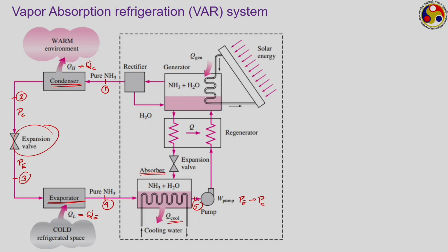Now, in the compressor, what is our working medium? Our working medium is a vapor. So, we know that this being a steady flow device, or an open system, the work input requirement W dot in, or maybe just W in, let us remove the rate, is generally represented as the integral of minus V dP, starting from the evaporator pressure level to the condenser pressure level. If these two pressures, PE and PC, remain the same, then the magnitude of this input work requirement definitely depends on the specific volume of the working medium.